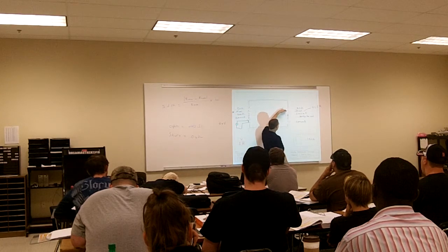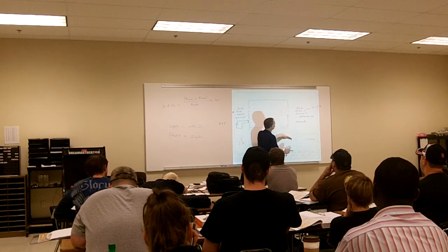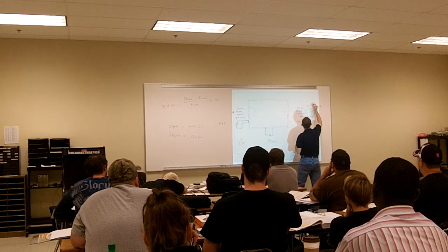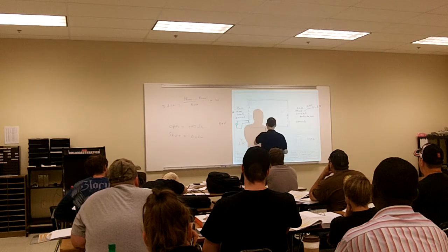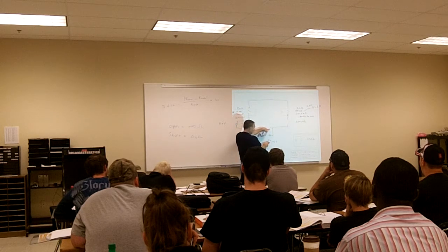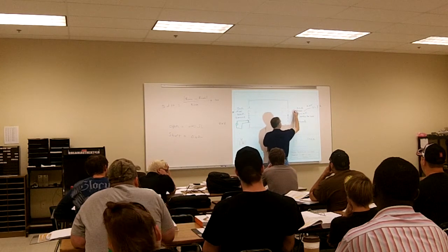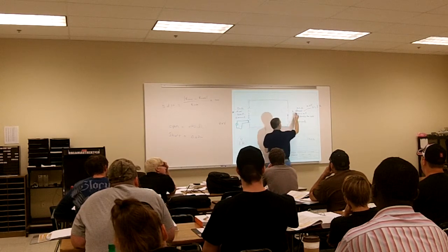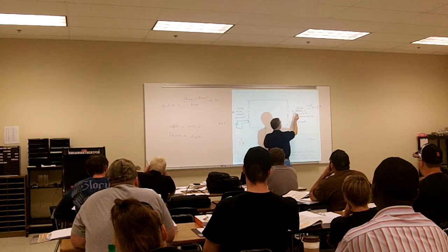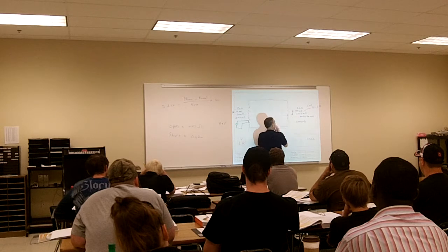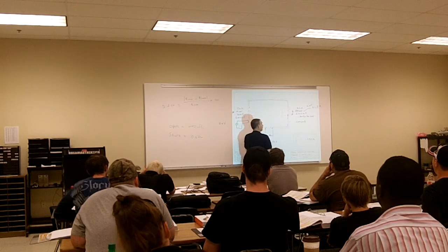And am I going to get any voltage across my resistor? No. Because this is going to go down to 0 volts, because my switch took all the voltage. There's no more voltage left to give to the resistor. So my voltage across my resistor went down. My current did what? Went down, because I don't have any current flow.